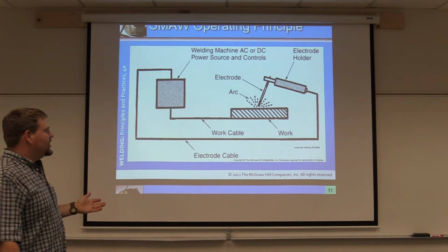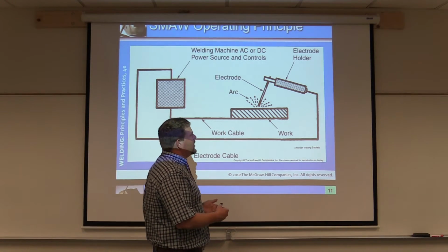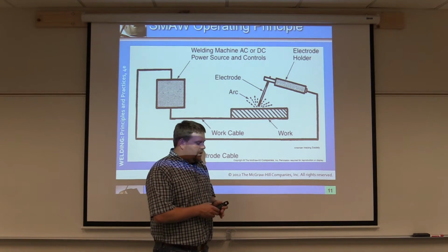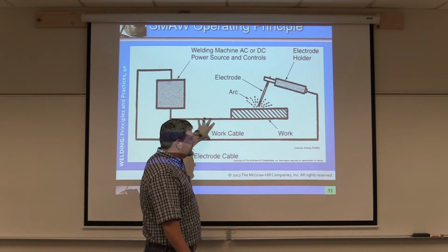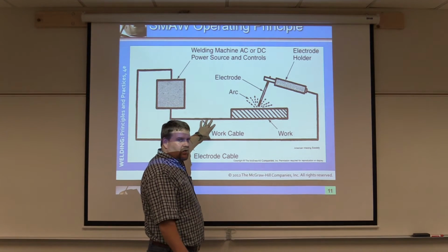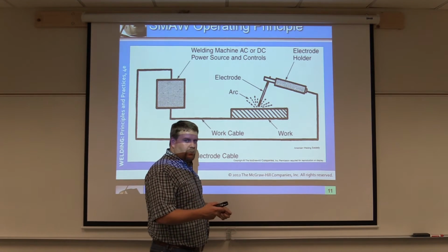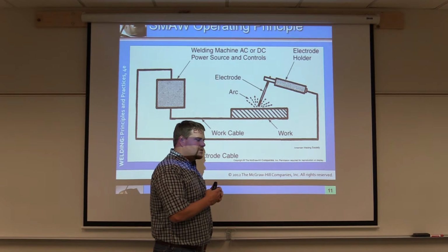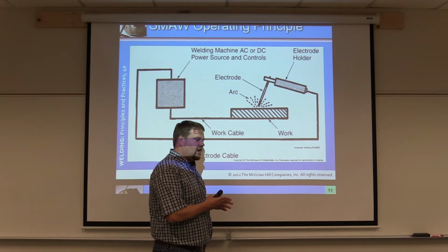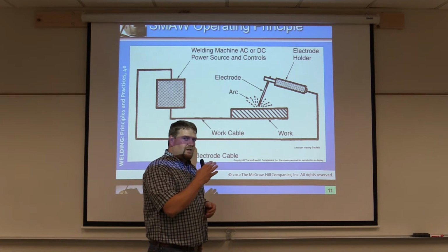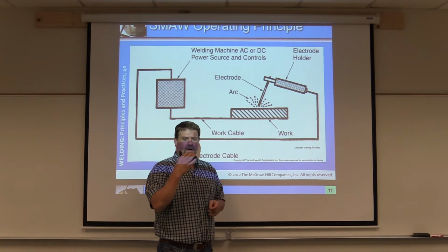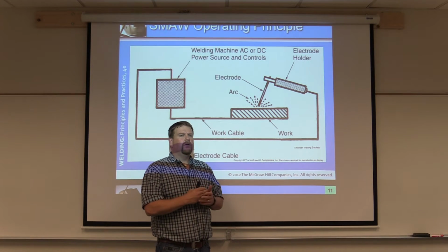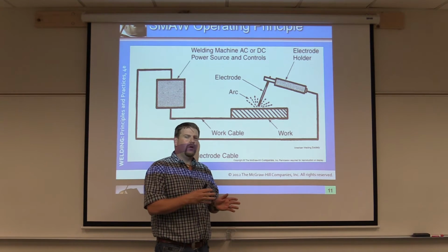But just to give you an example, when we're writing procedure qualification records, or proving procedure qualification records of a procedure, and when I test welders, a lot of times I will check the voltage within their machine, what is going on between ground and positive, to see how many volts are going. There's usually a window. Say you're set at 18 volts, the welding procedure may tell you it can only be between 18 to 23 volts. That's your window. If somebody's trying to drop it down to 16, you're out of the range, and that procedure is no longer valid.